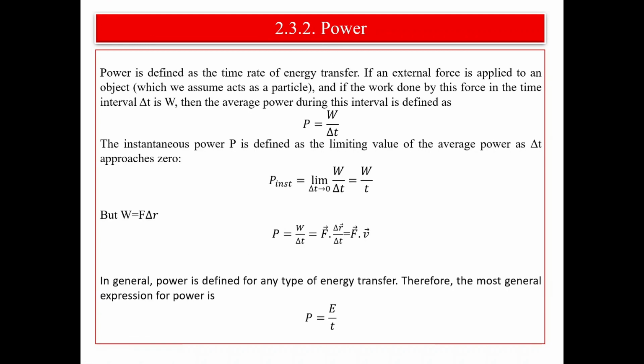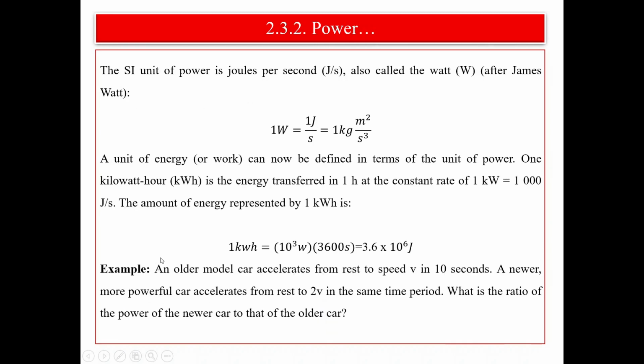So this 1 kilowatt hour, let's go back to this formula. This is the power measured in a watt, multiplied by time, it becomes watt hour. So if you use K, kilowatt hour is equal to the energy. Power is energy over time. So the energy consumption, multiplying both sides by T, power multiplied by T represents the energy consumption. So in most cases, kilowatt hour is representative of the energy transfer in 1 hour.